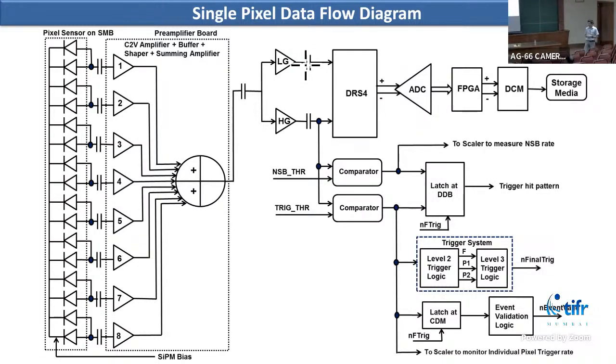So Sandeep, essentially what you are saying is you are not making any distinction. You are going to record both data, and you pick the one that is closest to saturation, meaning the maximum gain that is not saturated. Yeah. The saturation happens in the digitizer. So you have to digitize 1500 photoelectron information within the range given by the digitizer. The other one is just to find the gain for gain calibration.